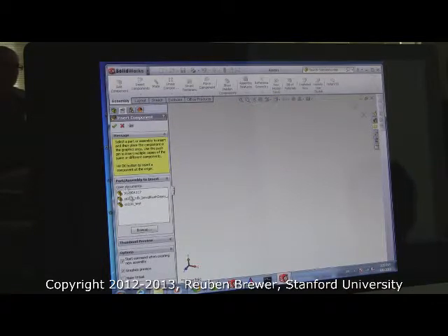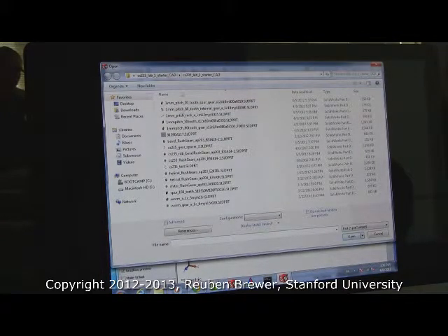See this that says open documents. Say I have 10,000 parts to choose from, but only 3 are open. It will look just the same here. If you can't find a part, that means it's not open. Go to Browse. Now we can do all of our parts.